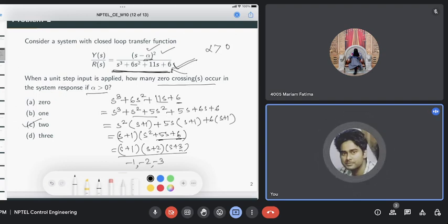Also this stability can be verified by Routh theory, so you can write this. So the stability for this characteristic equation, this is 1, 11, 6, 6, so it will be 60 by 6, 10, 0 and 6, so there is no sign change, so we see that all the poles are located in the left hand plane, right?